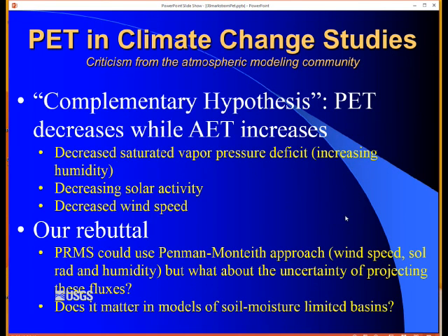And I just put this in here. This is kind of a personal issue. We've had a lot of questions about PRMS related to using these temperature index methods. The problem, or I don't know if it's the problem, but the issue is that as temperature increases, so does potential ET, because potential ET is a function of temperature, of only temperature, in all but the Penman-Monteith method.